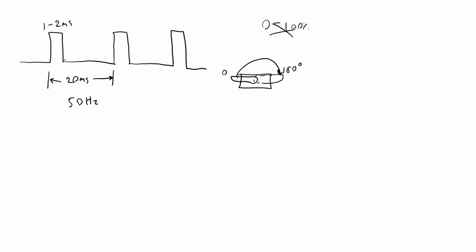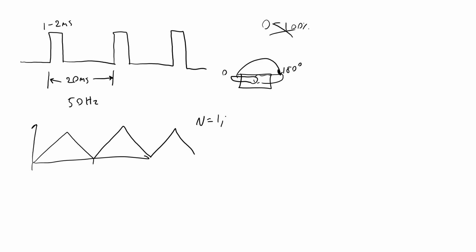We are asking, okay, how do we generate this PWM signal if the frequency of our square wave is kind of fixed by the amount of time it takes the counter to count up and back down, and I only have these fixed prescaler values, so 1, 8, and so on, so I can't really easily fine-tune this frequency or period to get an exact 20 millisecond period.